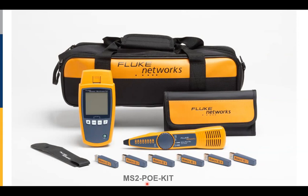Now, if I plug into an outlet and I don't see a switch on the far end, and I see that it's open 30 meters, 100 feet away, I need to find what port on the patch panel I'm attached to. And if it's not identified, this inductive probe is extremely useful.